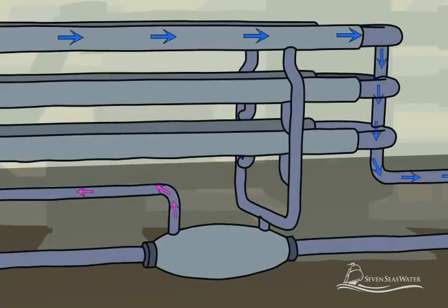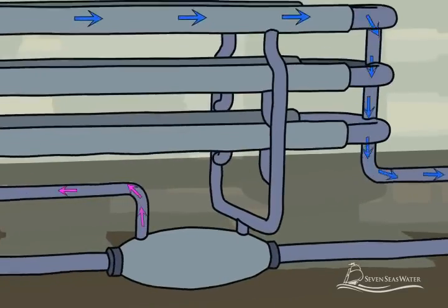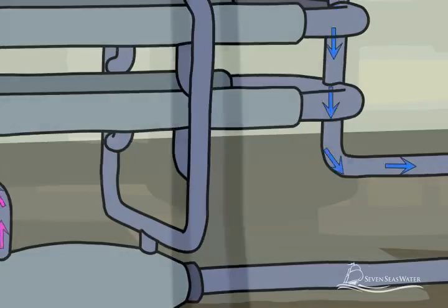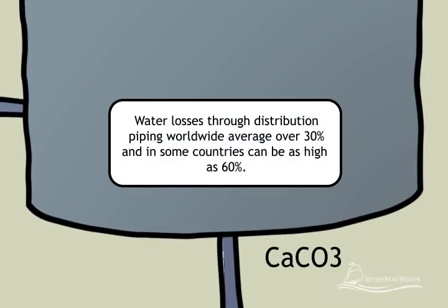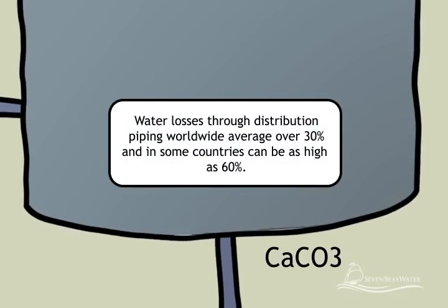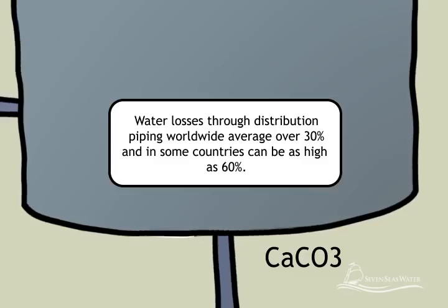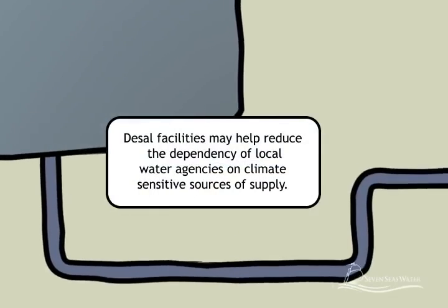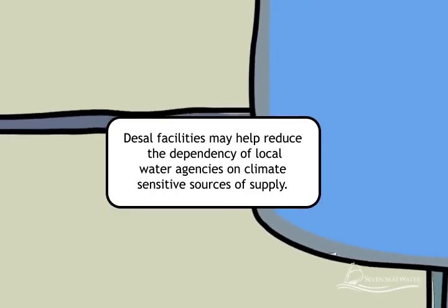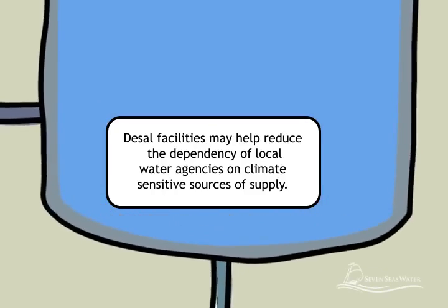Approximately 40% of the seawater that enters the system is converted to potable water during the reverse osmosis process. The potable water is further treated by adding calcium carbonate to improve the taste and bring the pH to the neutral range. Chlorine is also injected to provide disinfection properties as the water travels from the reverse osmosis plant through the distribution pipes to homes and businesses.